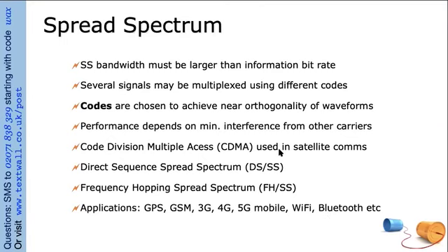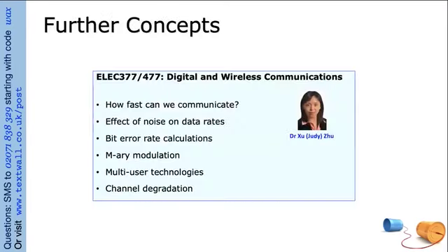So when we talk about TDM, that's generally for digital telephones. When we talk about FDM, it's for analog sharing of the frequency channel. But spread spectrum, that's all for our high speed digital communications. All of these applications rely heavily on different forms of spread spectrum. Not always frequency hopping, but it's the same general idea. So that's all you really need to know about spread spectrum.